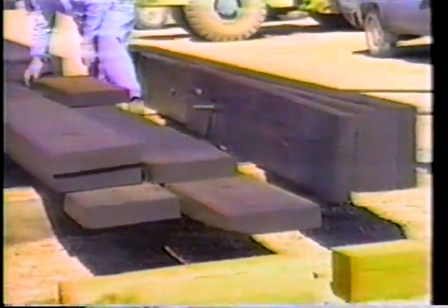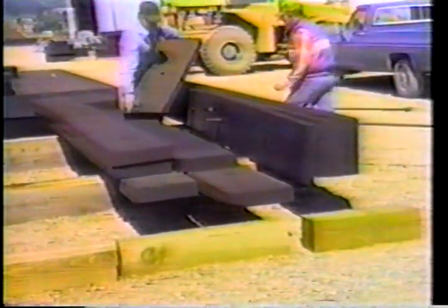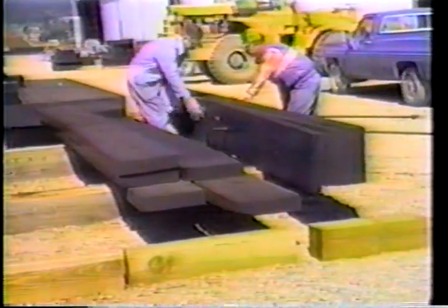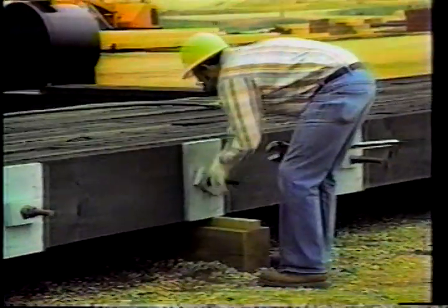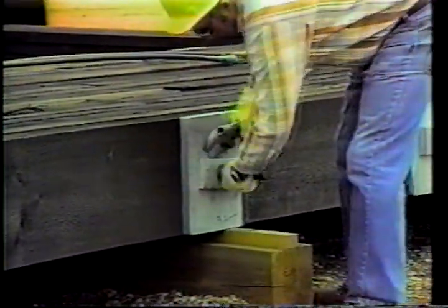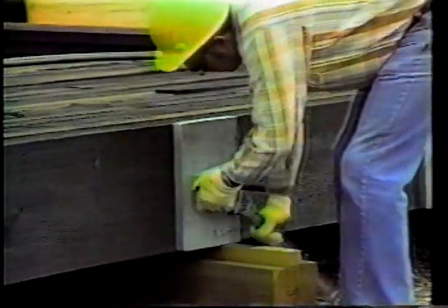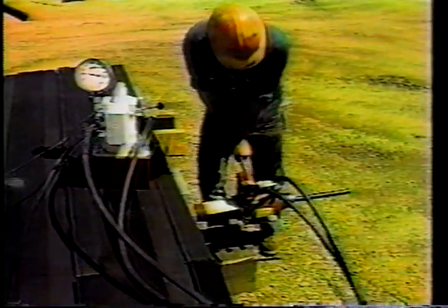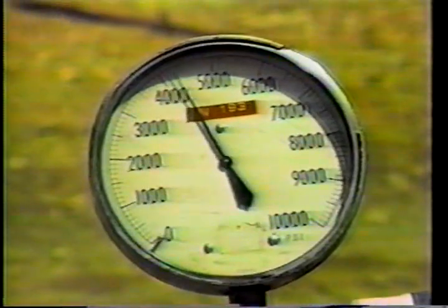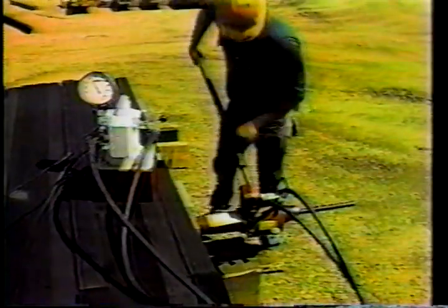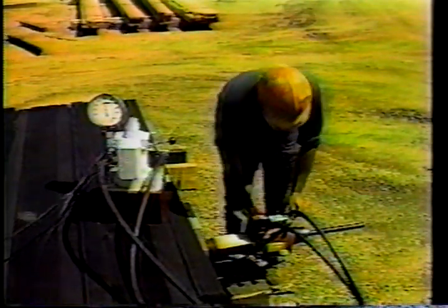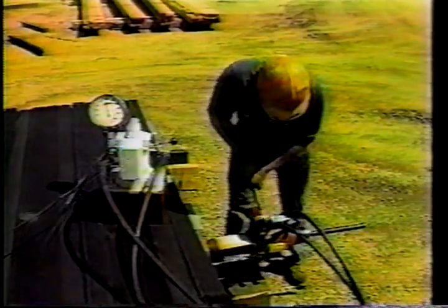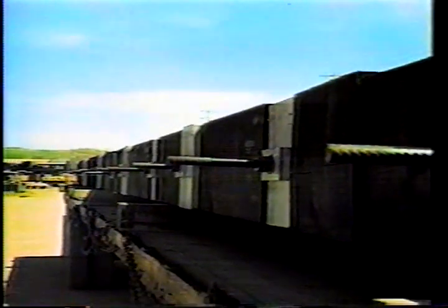Now the treated wood is prepared for assembly. Shipping rods are threaded through the pieces, pre-drilled and pre-formed. The rods are tightened and stressed. This stressing procedure is much the same as you will see in the actual erection of this post-stress bridge. The stressing is sufficient to keep the bridge pieces from separating. The loaded deck is then shipped to the bridge site.